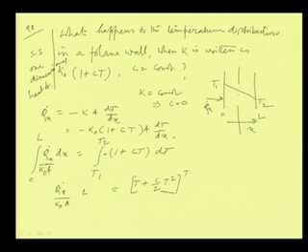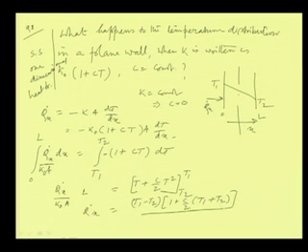So from there we can write that Q dot x is equal to T1 minus T2, into 1 plus C by 2 into T1 plus T2, divided by L over K naught A. This last part is the resistance, this is the driving force, and this is the extra term.